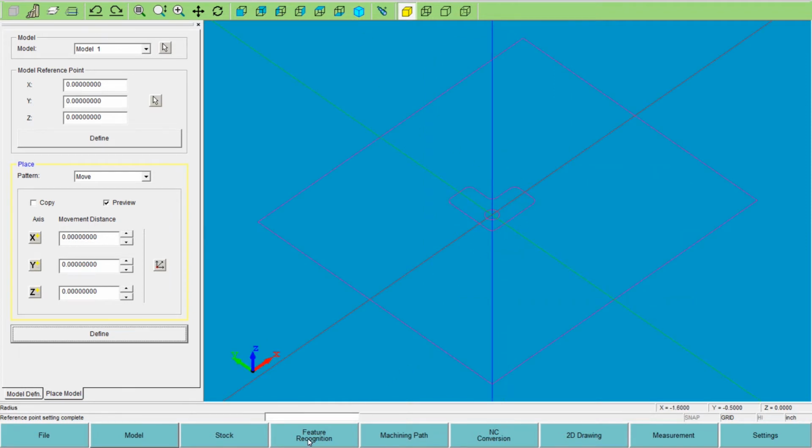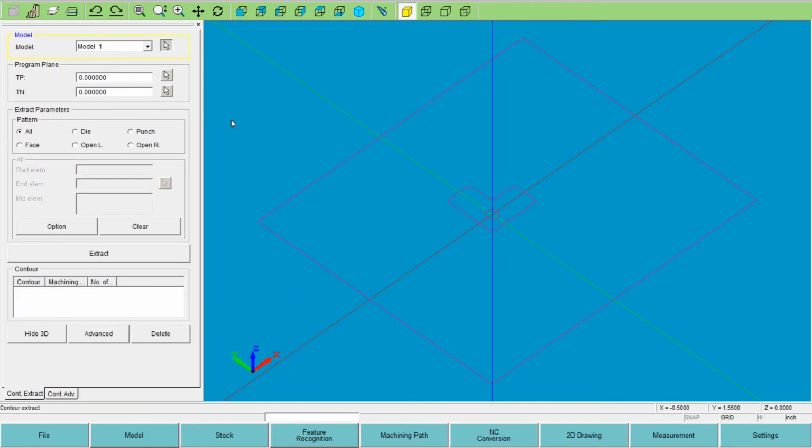So next step is our feature recognition and contour extraction. Our wire cut blocks, I believe they are 3/4 of an inch actually. So what I want to do is cut this size that's in the drawing. Obviously it comes in at Z0, just flat, but we're making it like a 3D shape. So what I actually want is to put that plane, or this geometry, at the top plane, which would be the top of my block here.